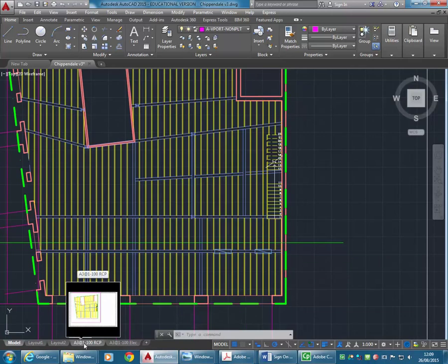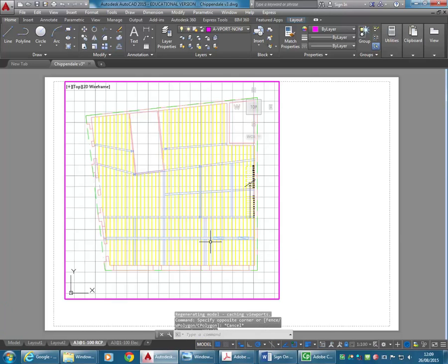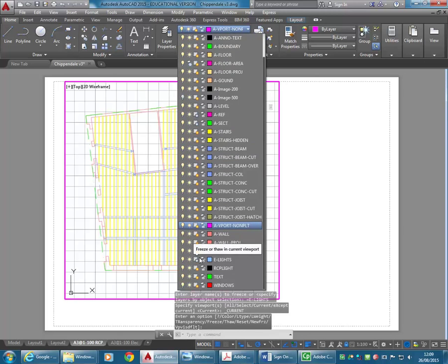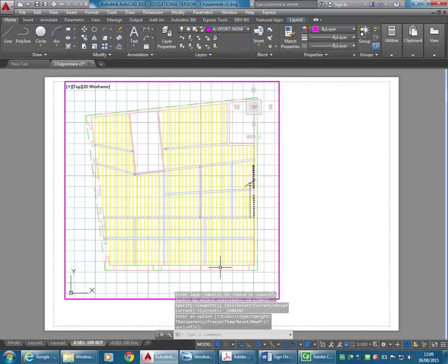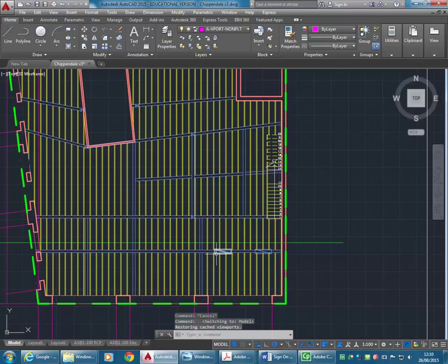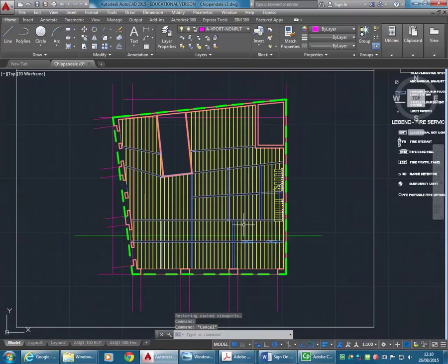And then on the reflected ceiling plan, we don't need to show the lights. Or we may, actually, but it's optional. So here, if you wanted to, because they're on an electrical layer now, they could be frozen there. So that's a good way of setting everything up. And then you can just continue placing lights by either inserting or copying those blocks. But I'll let you work that out going through the photos.